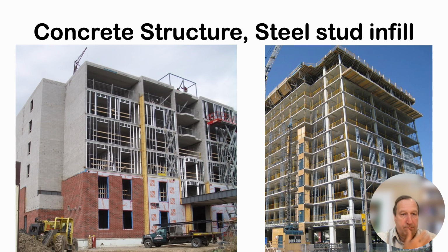So here I'm showing you some images from the Waterloo region showing concrete frame with masonry as a shear wall. That's the concrete block on the left-hand side. And then on the opening side, where they have lots of windows and openings, they're actually installing steel studs with openings, and the shear wall you can't see is hidden behind at the corridor.